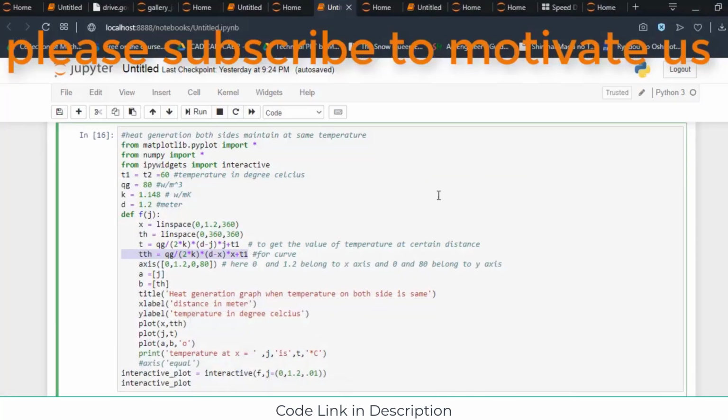So now let's try to understand this code if you know about heat transfer. First of all, I import the graph libraries, NumPy, numerical Python libraries and IPyWidgets. Here I considered the slab temperature at both sides as 60 degrees Celsius. Qg, that is heat generation per unit volume, is 80 watt per meter cube and thermal conductivity is 1.148 watt per meter Kelvin. Here D is basically the thickness of the slab, that is 1.2 meter.